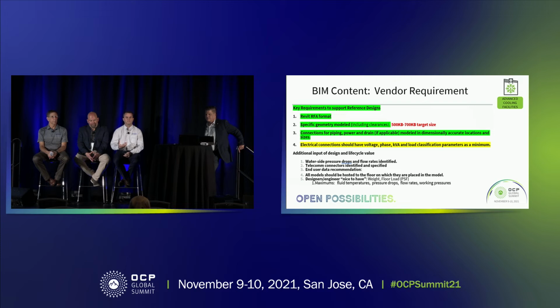But what we frequently get from manufacturers is their STEP file from fabrication, right? The 3D file that goes into the machine that punches all the holes and everything. In the 3D software that is typically used by many design firms in the industry, every single little geometric shape in that piece is getting rendered by the GPU in that workstation. So if you've got 378 holes punched in that sheet metal, the software is going to try to render 378 holes.